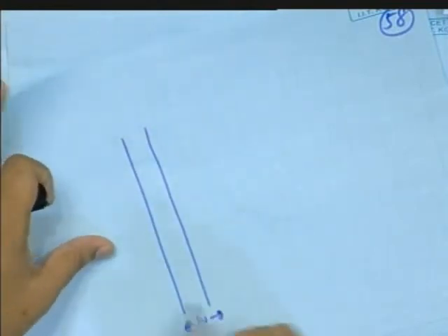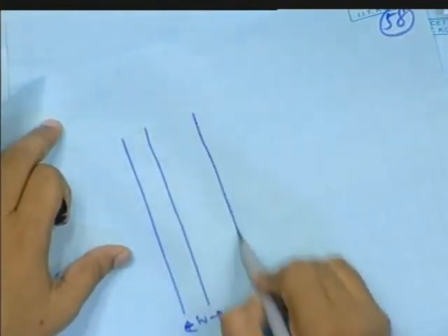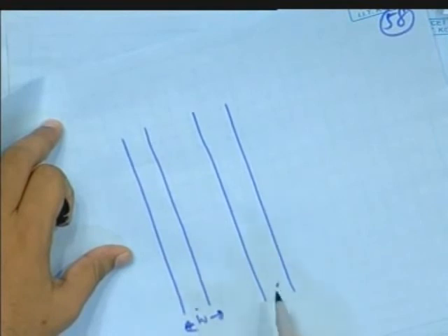This is one DRC. The gap between two metal wires, center to center, has to be a minimum of say d. This is one constraint. You can define your own constraints also. Metal one, you cannot connect to ground. This could be your DRC. That is written in your text file.